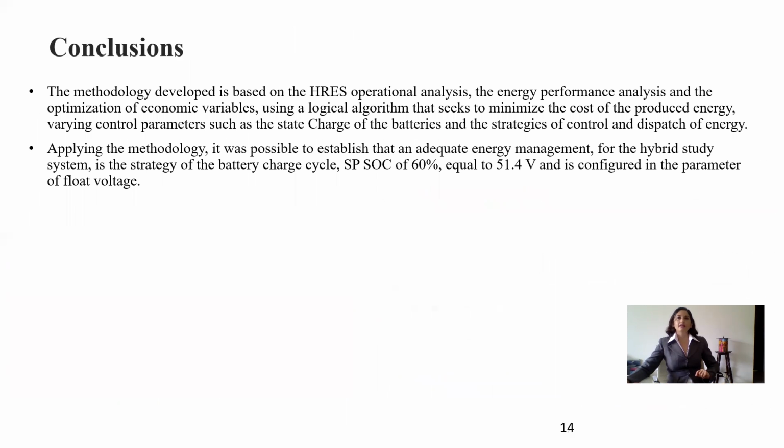Conclusions. The methodology developed is based on HRES operational analysis, the energy performance analysis, and the optimization of economic variables, using a logical algorithm that seeks to minimize the cost of the energy produced, varying the control parameters such as the state of charge of batteries and the strategies of control and dispatch of energy.